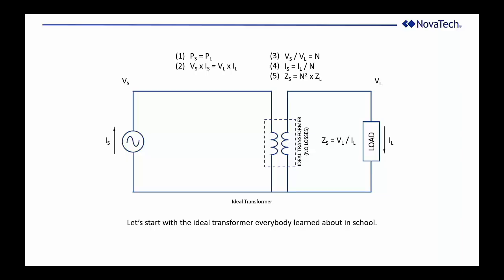Usually there are, of course, step-up transformers. Usually GSUs, generator step-up transformers, will boost the voltage from maybe 35 kV up to transmission levels. But most of the utilities who are doing loss compensation are receiving power from a transmission utility, and they may have, let's say, their meter on the low voltage side.